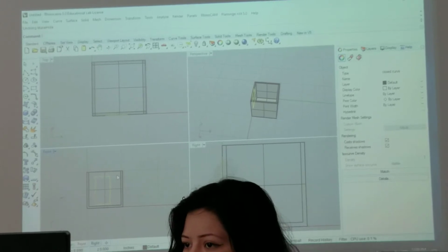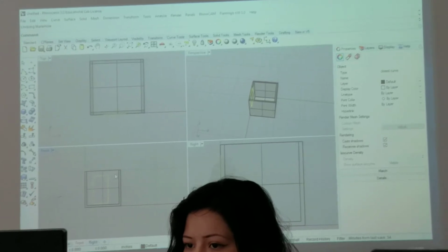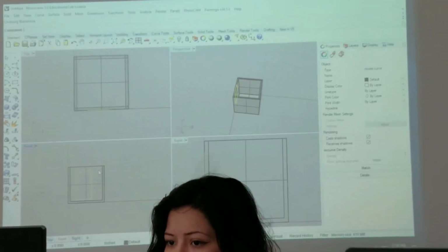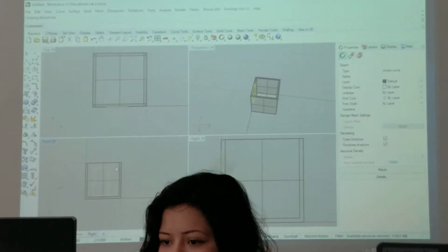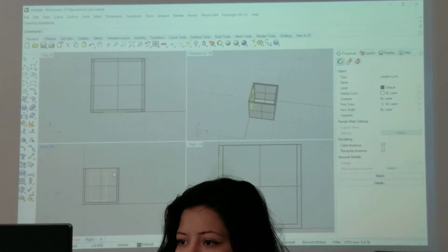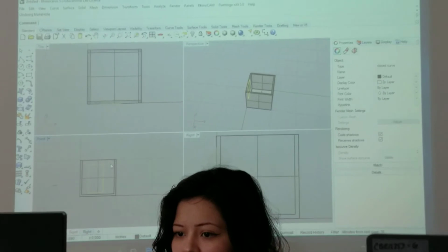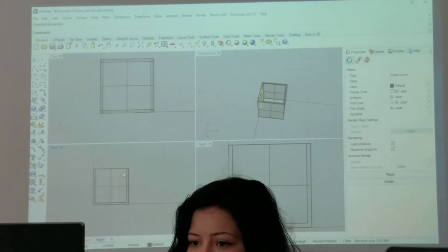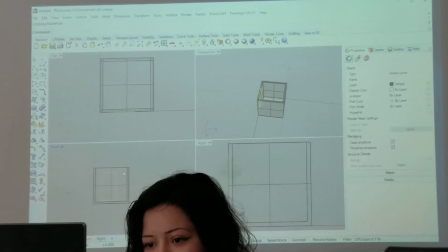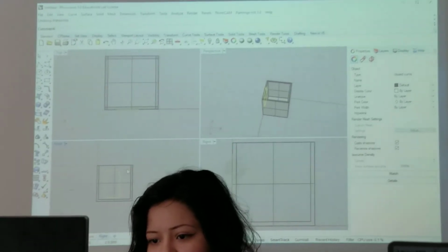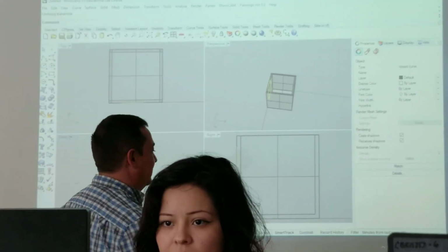Select the surface you want to make a hole in. You're going to need to click on the line of that surface because it's not shaded. So click on it anywhere there's a line in that view. Click on the line anywhere on that object. There you go. Alright, and then if you look at the top view, you should be able to use your mouse to control how deep it's going. Or you can just hit enter. But what did you click? These ones. So you're going to need to do make hole again. Also, you did not join your surfaces before you offset them.